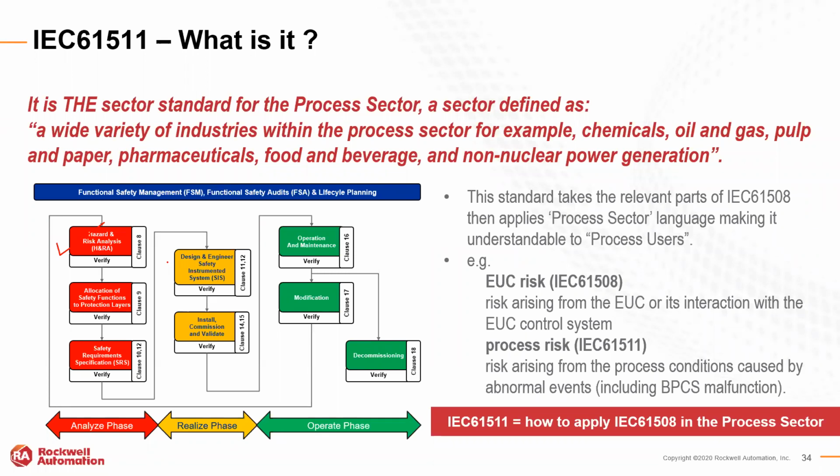So what are the hazards? What is the risk? What is the likelihood? What is the consequence? Maybe the consequence is that it'll blow up the entire facility. Well, okay, but what's the likelihood of that happening? Well, it's 0.00001. Okay, well, we're going to put a pretty low SIL on that because that doesn't really matter a whole lot in the day-to-day operations. But you go through and you identify all that.